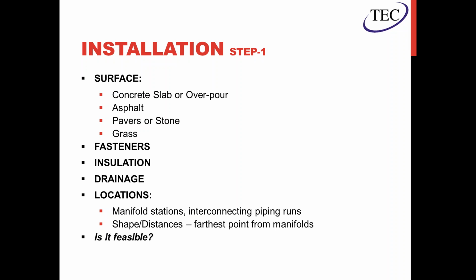And then in terms of pavers and asphalt, you do want some sand covering the tube, but it's not 2 inches. In that case, you want to refer to the individual manufacturer. I can pull out a diagram towards the end of the presentation if we have time to go through that a little further.